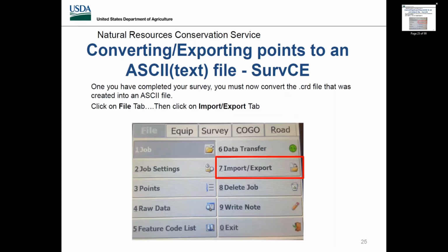Hey, Dan. Remember when you were just saying that it should exclude points 1 through 99 as well as 3,000 and 9,999? I didn't think it did, and I just looked at the point group properties for existing ground on my open drawing, and it does not have 1 through 99 on there.